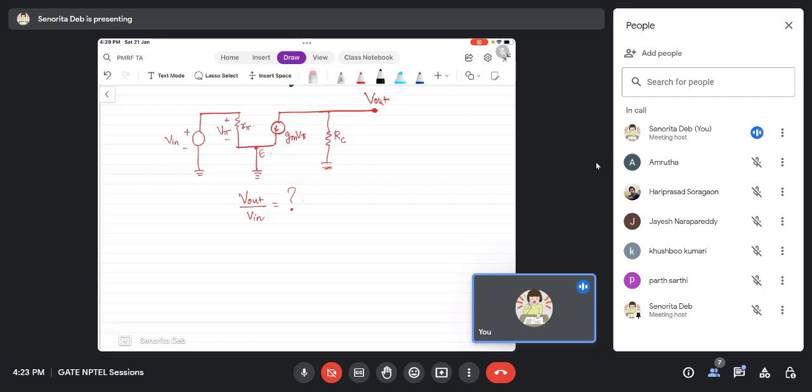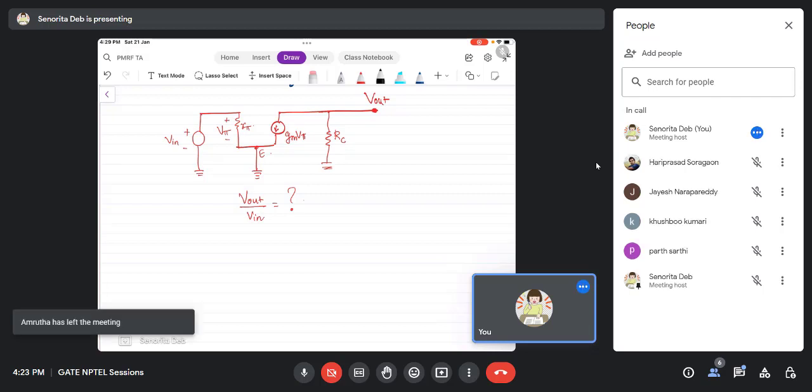So in this kind of a circuit, if I ask you what is the V out and V in relationship, you don't see any direct thing between the two, right? So what you do, this node is V out. This you have understood? This is V out. Now this is V in. Here it is easy to apply KVL, and here it is easy to apply KCL, because there is a common node and a current source. Therefore easier to apply KCL.